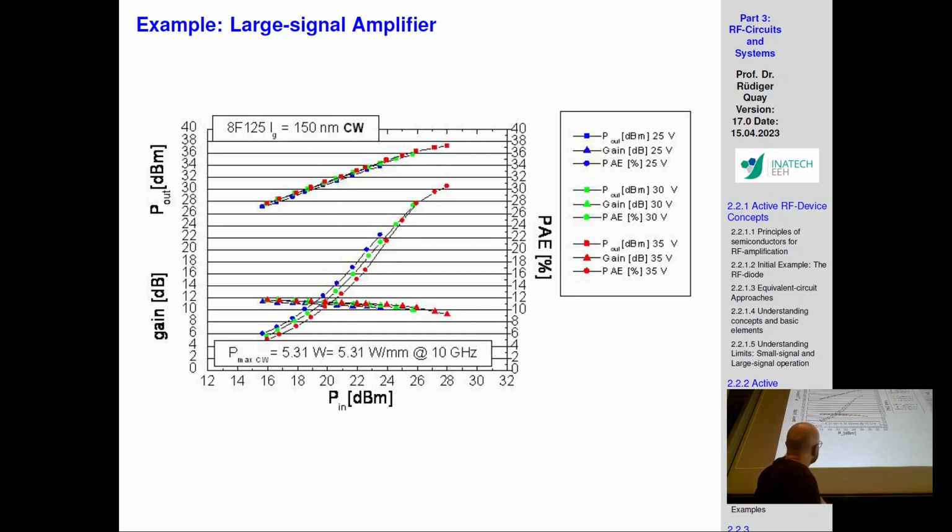It remains flat. For 16, for 18, for 20 dBm input power, the gain is flat. The device is constantly producing the same amount of gain. That means that your device is behaving, in the sense that it still hasn't entered saturation, it's behaving linearly. So it's providing you with a continuous gain from what you put in your input and what you get from your output.